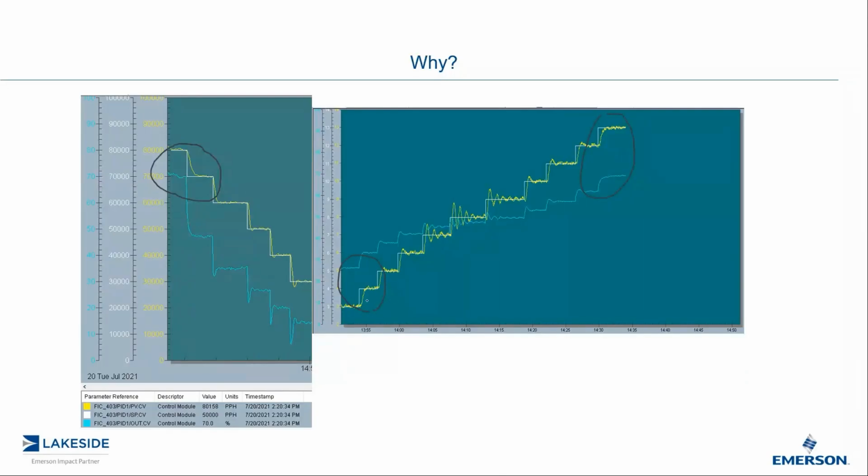But as you remember, the titration curve for a strong acid, strong base is like this. The process becomes very sensitive around a pH of 7. So once again, knowing how the process changes will force us to consider a different control strategy.